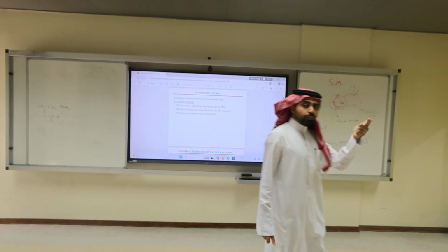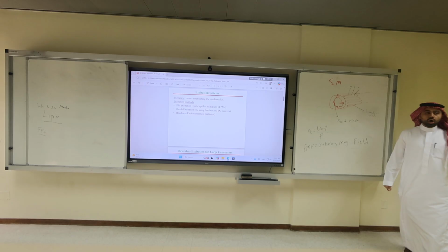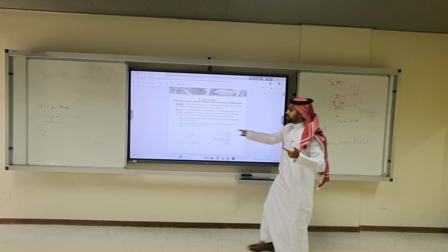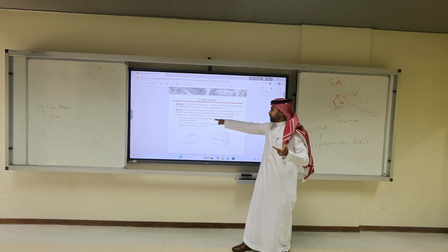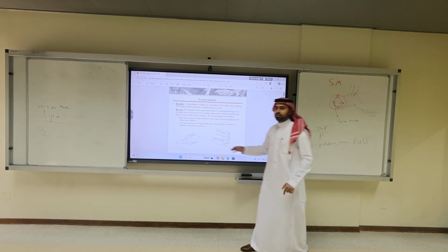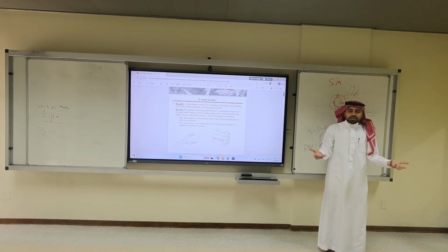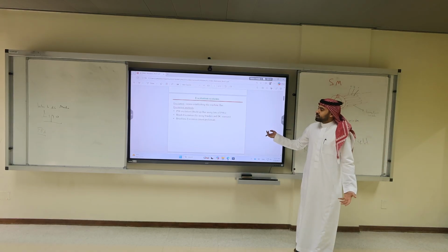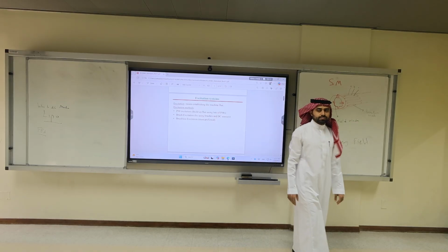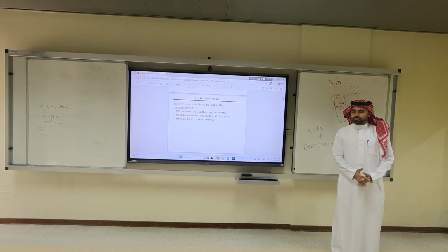So we expect the number of poles in Tesla to be high or low? Low. Because it's going to be from this category: high-speed machine with cylindrical rotors, several hundred megawatts. This is for the case of the generator. But for Tesla, it's a small machine. So the number of poles is less. So in Tesla, I don't need to have the other two types of excitation because I can put permanent magnets. The problem with permanent magnets is that they demagnetize over time.